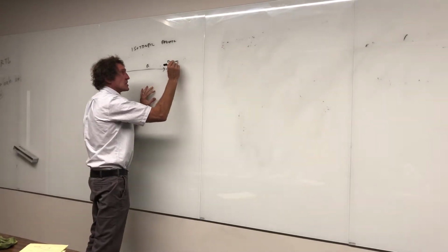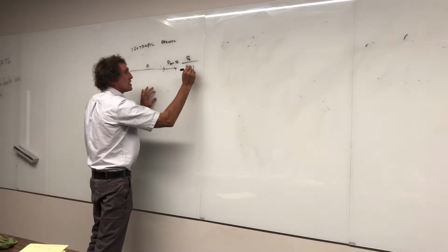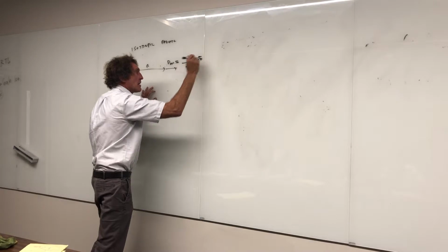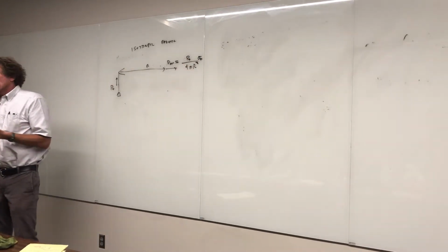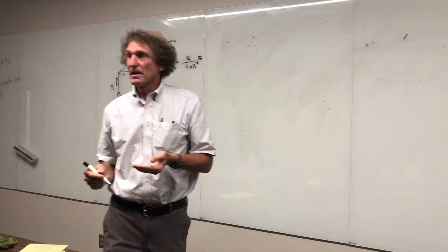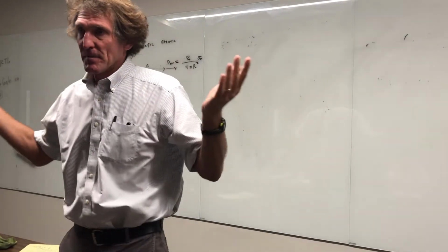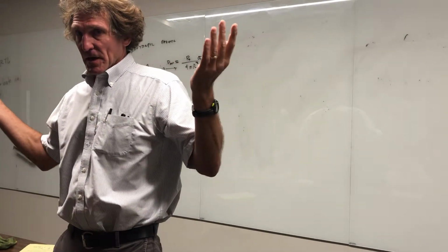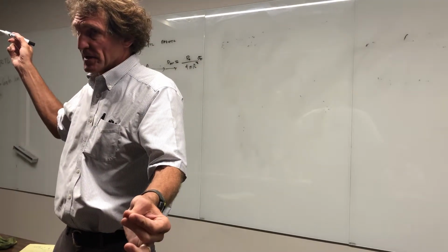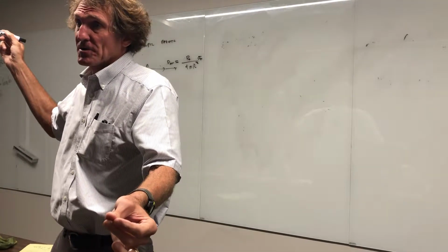And the way you get it is just take the total power radiated over the surface area of a sphere. And that would be actually the average power density from an isotropic radiator. Can anybody give me an example of an approximate isotropic radiator? I know you know it, from anything. Anything. It doesn't have to be an antenna, man-made source. How about the sun? If you come out from the sun a given distance, right? The intensity, radiation intensity, is the same regardless of what azimuth and what elevation you're at. Do y'all agree with that?